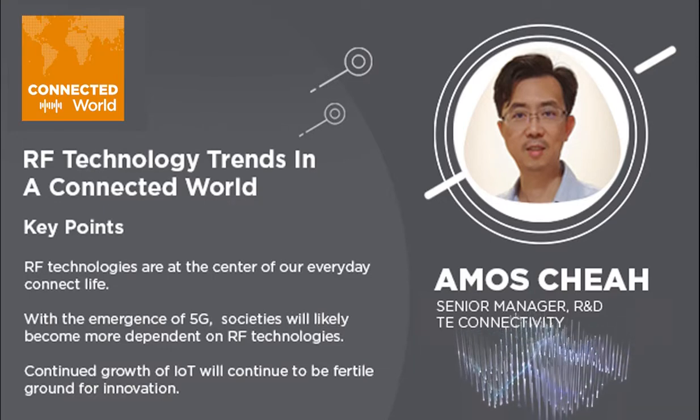From the technology standpoint, this will mean higher frequency, wider bandwidth, and higher efficiency power amplifiers are needed. Other needed components will include low noise floor LNA, quantized phase shifter, and also ultra low jitter clocks. Also low cost millimeter wave packaging needs to be developed, and also ultra high speed and low power AC to DC converter. Wideband antenna, millimeter wave antenna, a high gain directional antenna, and beamforming antenna need to be developed and will become a norm.